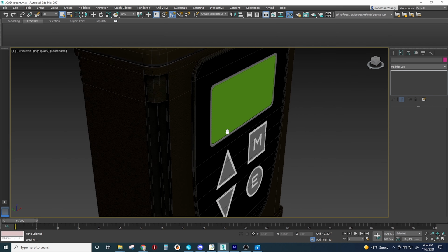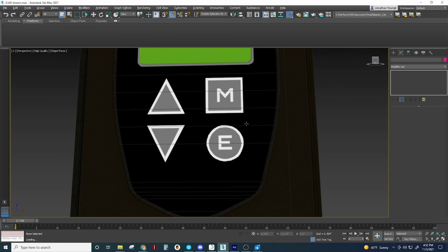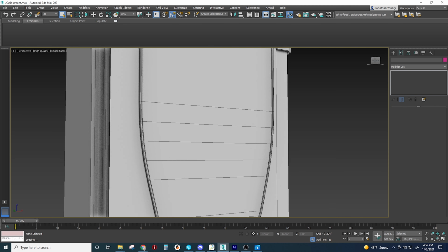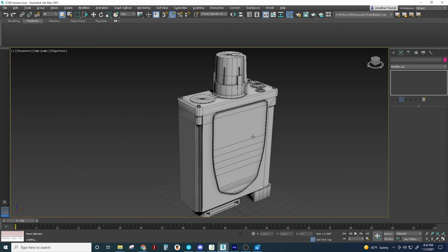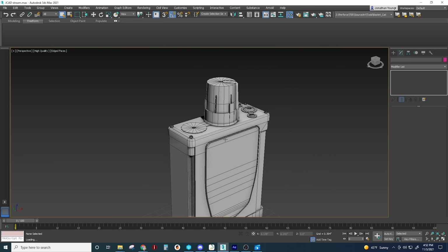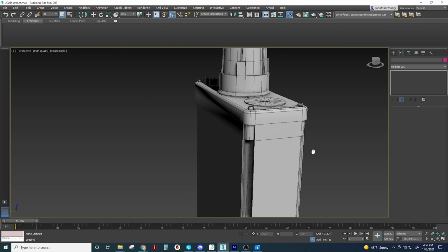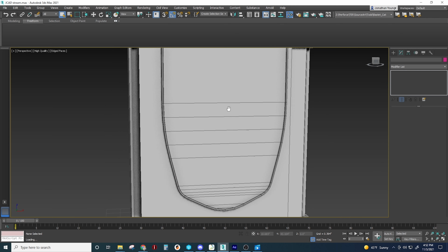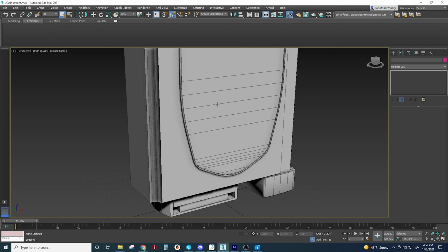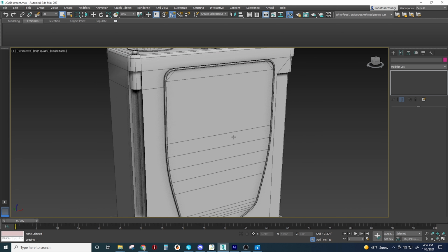These are all textured-on details. If I remove these textures, you can see what the actual geometry looks like. And the actual geometry is what's going to get 3D printed. So for certain things like the buttons on the front, if we want to run our finger across the surface, we need to have that detail modeled in so that there's a physical representation of that.